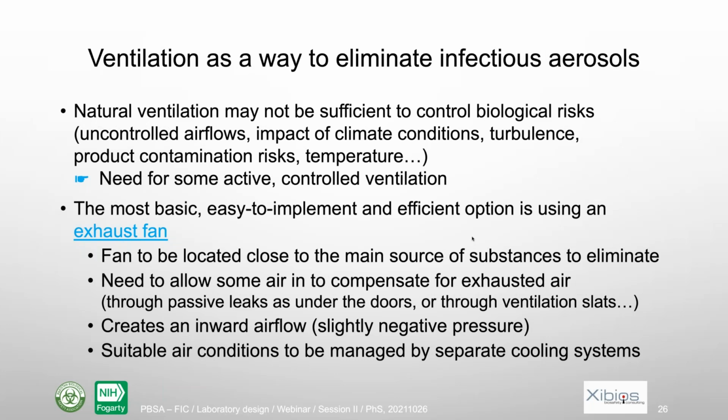And from that point of view, there is one solution which is easy to implement and very efficient in providing ventilation, is to use an exhaust fan. That means a fan that takes the air from the lab and sends that air to the outside.